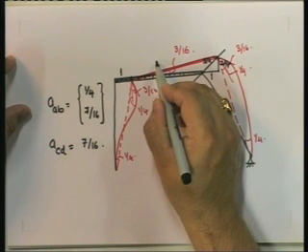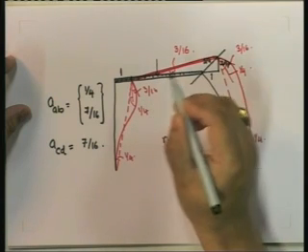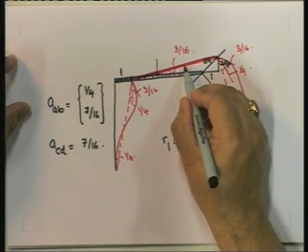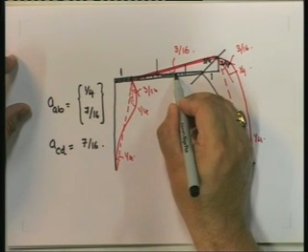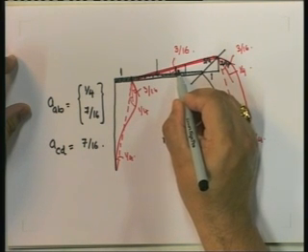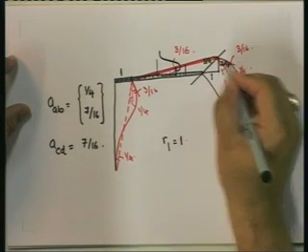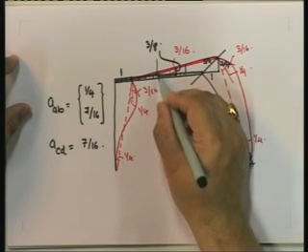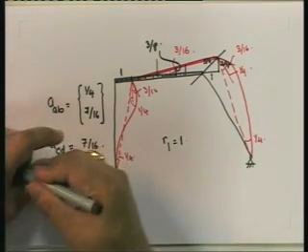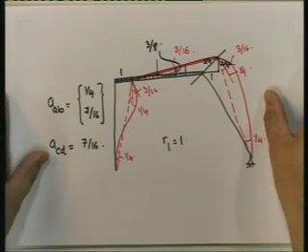Okay. Now note that this load over here, how much has that point, the central point, displaced by? The central point, by the way, has moved by 1. So how much is this? This is going to be half of 3/4, so this is going to be 3/8. So the load point has moved up by 3/8. This is going to play an important role in our calculations a little bit later. Okay. So now I have computed the theta AB.